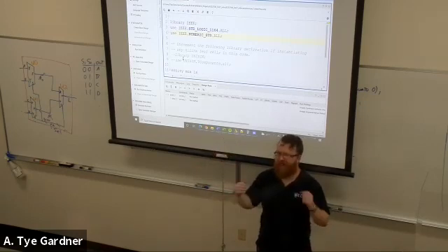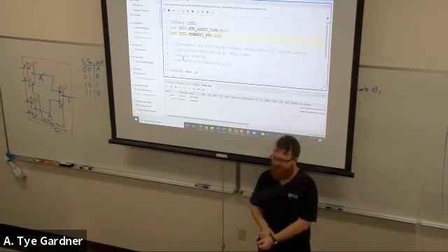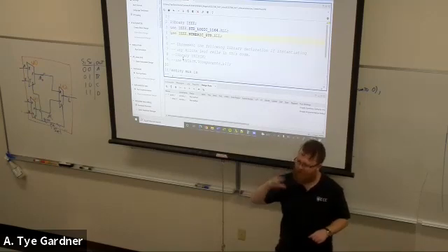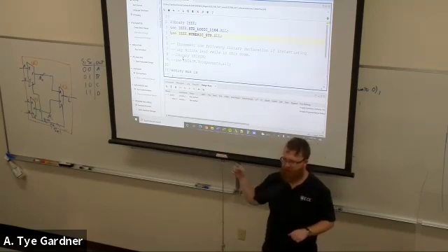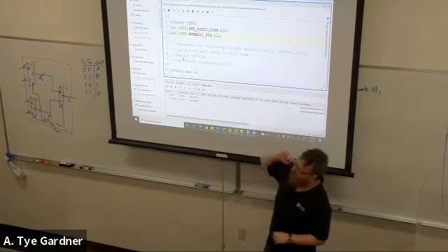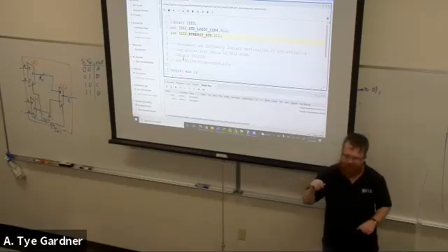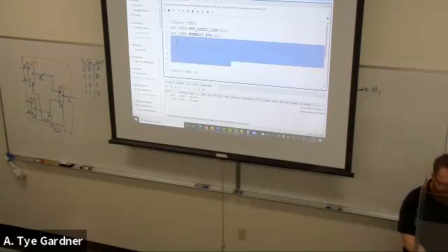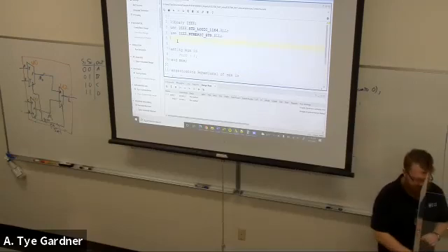They kind of communicate how you make things talk to each other nicely. If you use signed or unsigned libraries instead of the numeric standard, they're not really official, and so they may not work on all hardware. This is supposed to work on virtually all hardware. It's a universal standard. Okay, this Unisim stuff, you can just delete it out because we don't need it yet. You will eventually, but not yet.